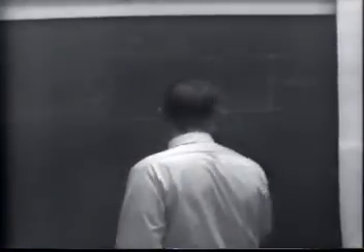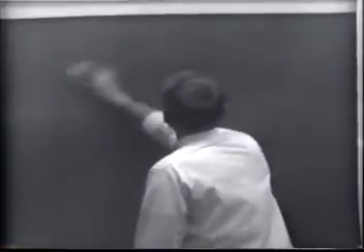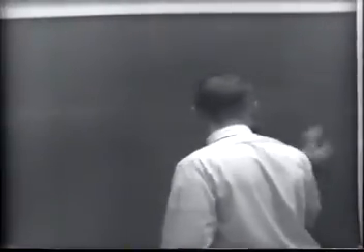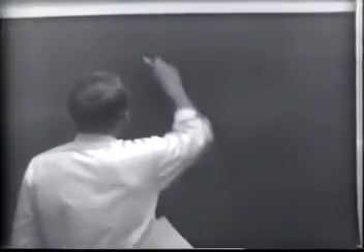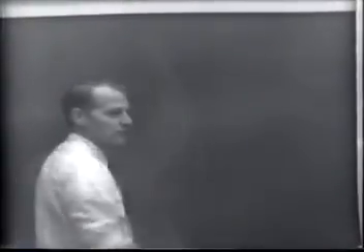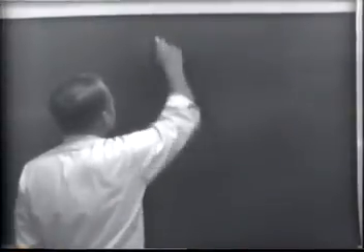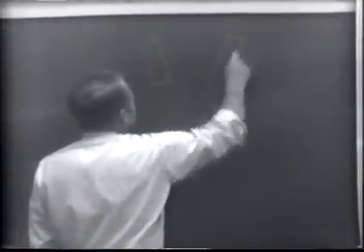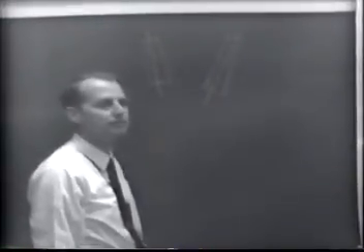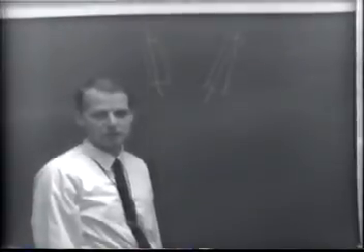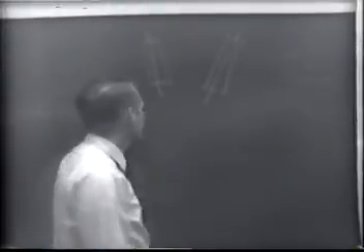Now let's look and see what some of the basic parts of a circuit breaker are going to look like. We might just do this on kind of a functional basis first without talking about any specific kind of breaker. First of all, we have a continuous current path. We have to have a conductor that's going to carry the continuous rating of that particular circuit breaker. This is the load current, the normal current through that line.